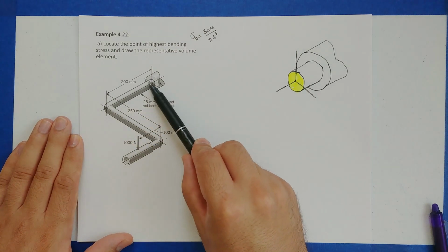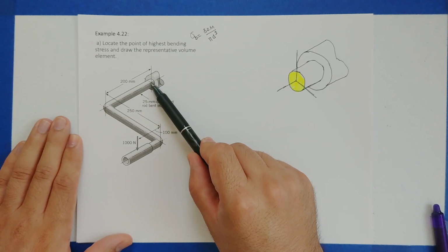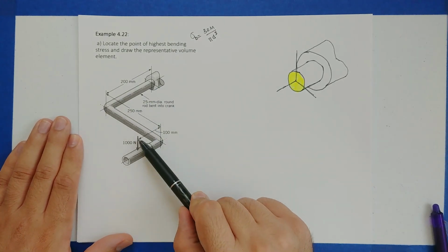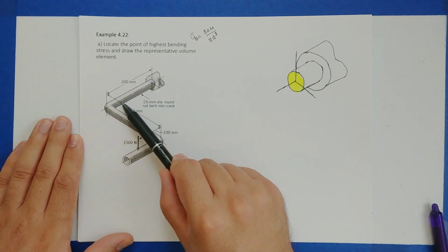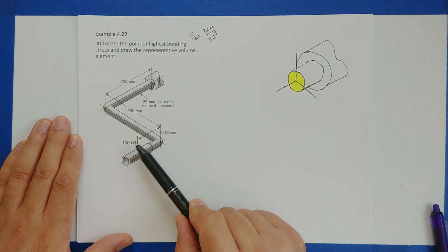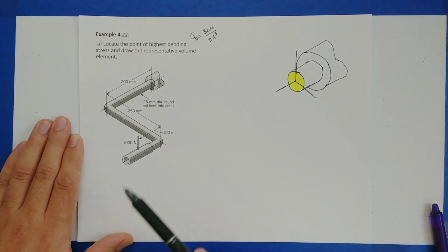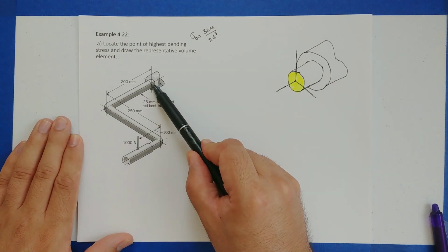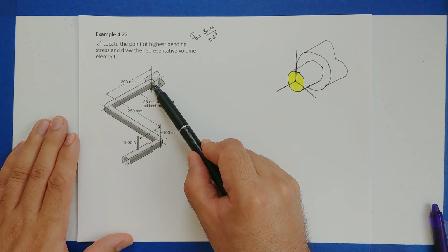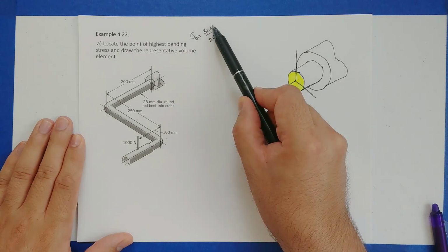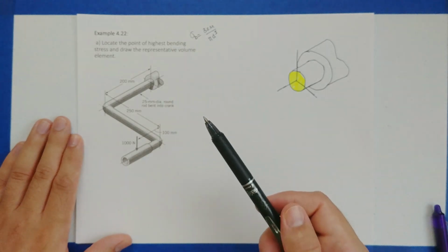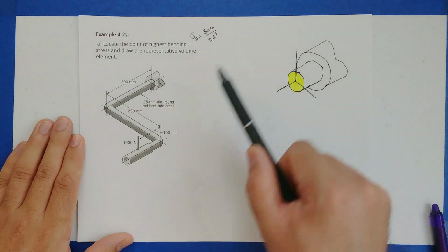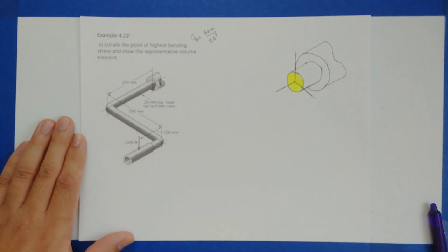And if we look at this last one over here, the distance is going to be the highest, right? So we have, again, 1,000 Newton, but the distance is going to be 200 plus another 100 over here, or 300. And so this point over here would be the point where we would have the highest bending. Again, what is a moment? It's a force times the distance. So where's that moment going to be biggest? Well, where the distance is biggest because the force is constant.